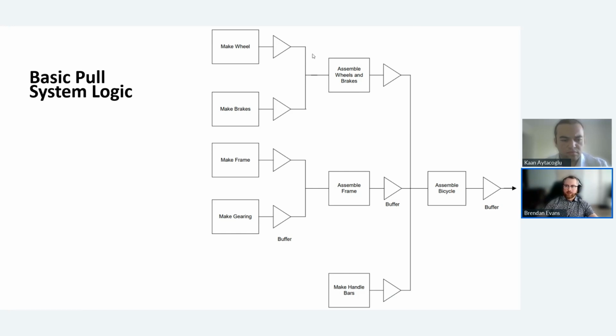Kanban is a way to replenish the inventory in each buffer using visual cues. As an example, you might use something like a 2-bin system where when one bin gets emptied, the next bin gets pulled forward and the first bin gets sent to production to replenish. You may use a single card or a multi-card system to indicate when you require replenishment or when you're out of stock.